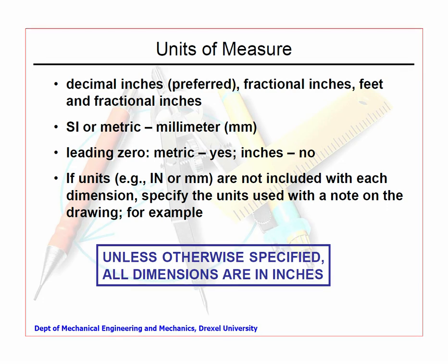And as we come down, the next very important thing, you see here, is the leading zero. That is, if something measures 0.5 millimeters, you write 0.5 millimeters, with the zero on the left side, because of the way the centering takes place and the way things are represented, and added to that is how occasionally they are all sorted, that 0 is required on the left side.